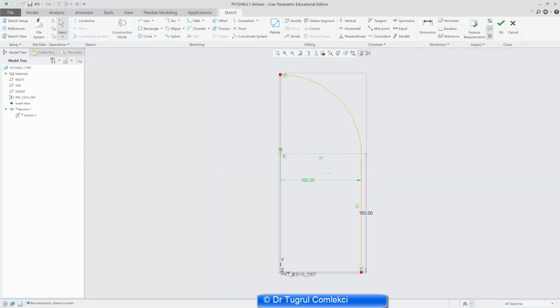So what I can do is add the half thickness to my internal radius. So I can do 100 plus thickness 1 divided by 2, so that is adding half of the thickness to the internal radius, and I can enter that, and it will replace the number defining the internal radius with this relation 100 plus thickness 1 over 2.